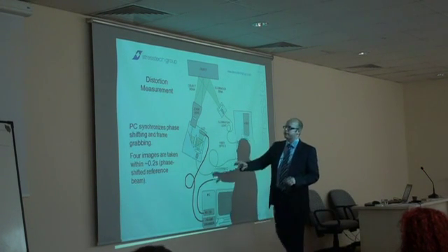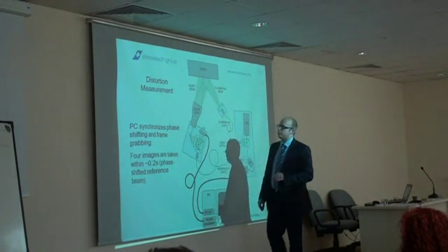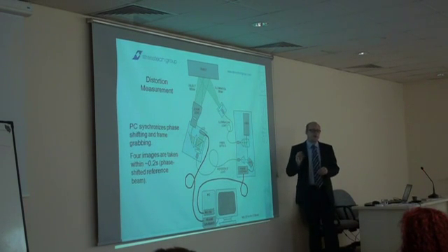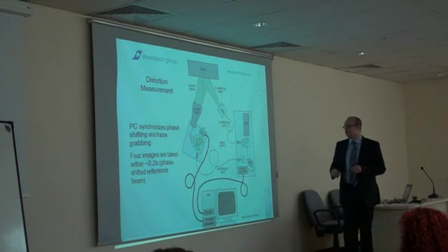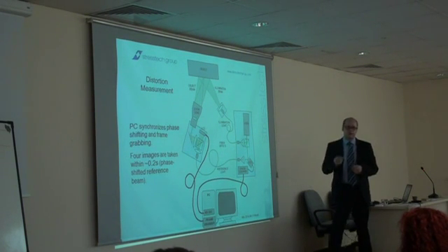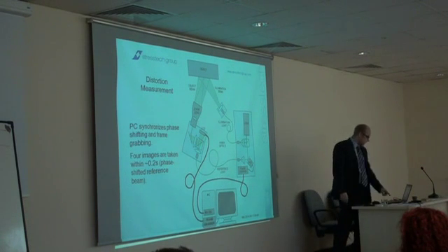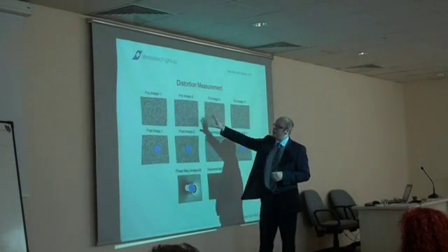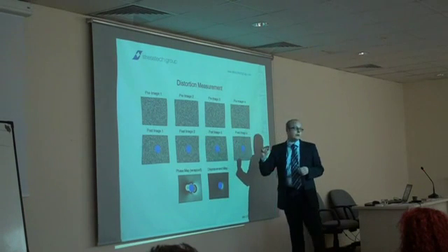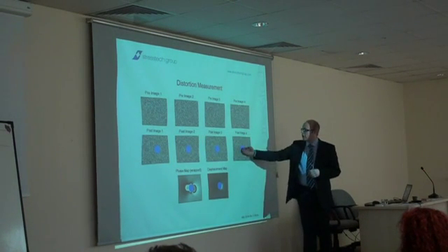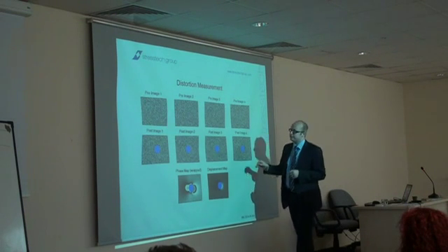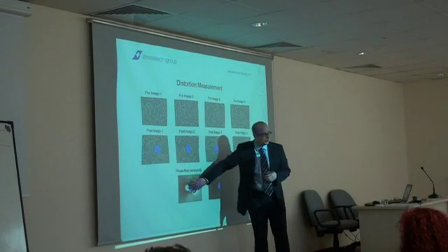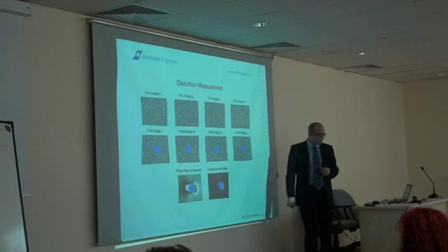Now here I would like to say that the PC synchronizes phase shifting and frame grabbing, and we can set up automated imaging and drilling. So users just have to give the parameters, push the play button and wait for the results. This pre-image is taken from the sample surface. Then we make a hole, and we take a new image set, and we put all of those 8 images together. We get a phase map and a displacement map.